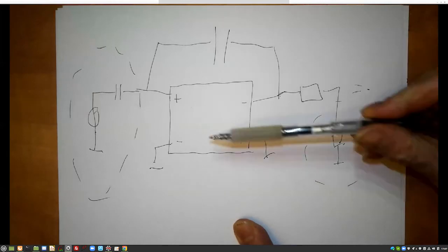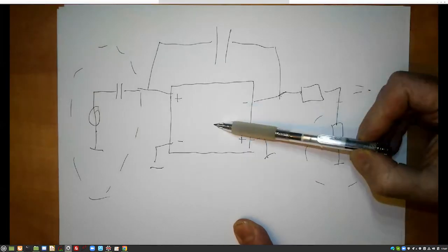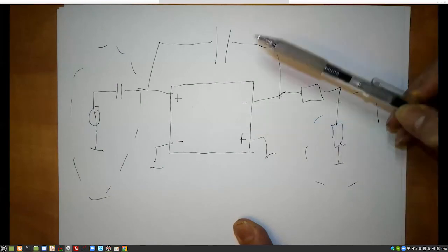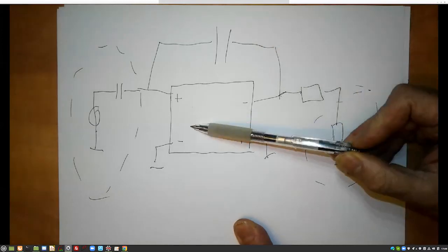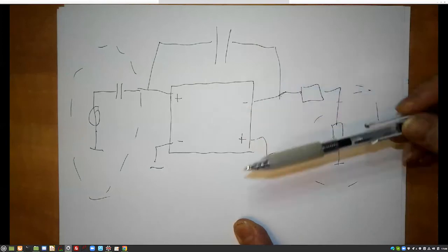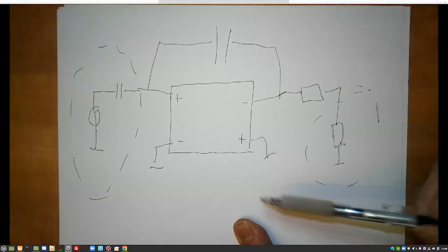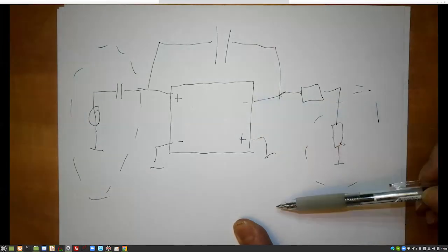I used a single CS stage, a current mirror for extra inversion, and then again a CS stage, but now complementary parallel. The question for you is to replace the combination of this single CS stage and the current mirror with a differential pair. So what we are going to do is design a controller and place it in this box. That is what we do.